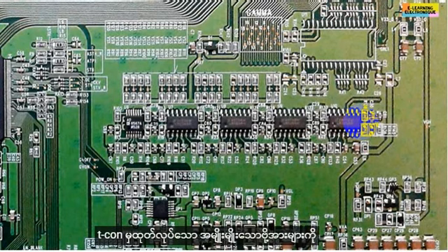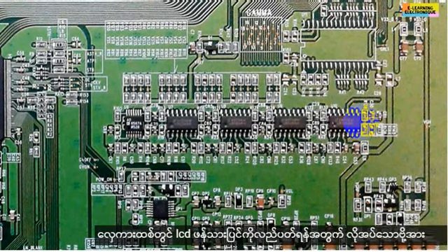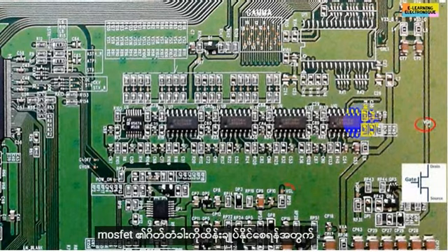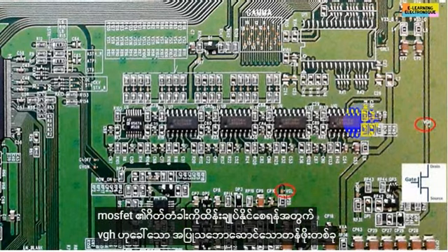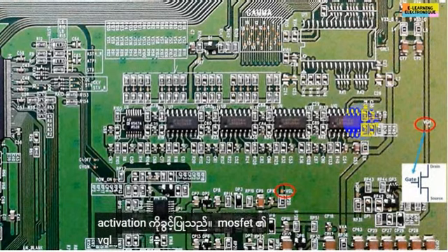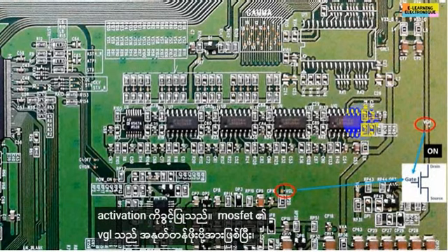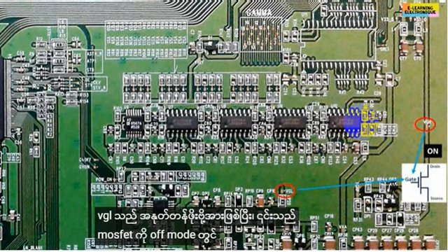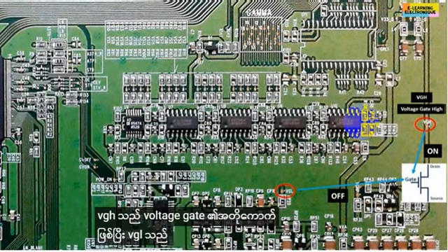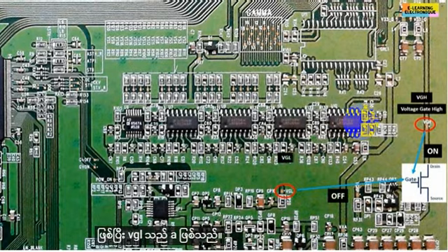Various voltages produced by the T-Con are necessary to operate the LCD screen. The latter contains MOSFET transistors. Two voltages generated by the T-Con allow the control of the gate of the MOSFET. A voltage of positive value called VGH allows the activation of the MOSFET. The VGL is a negative value voltage. It allows to put the MOSFET in off mode. The VGH is the acronym of voltage gate high and the VGL is the acronym of voltage gate low.